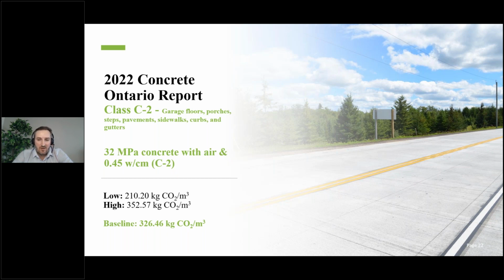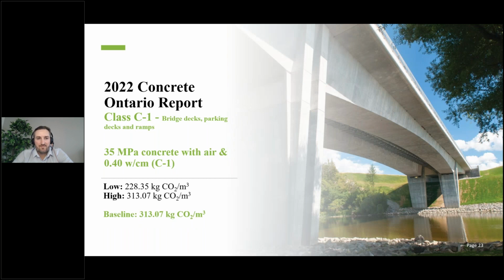And this is again based on industry average information. There are obviously type 3 verified EPDs that are out there where you can get even a much better performance. But overall, this is a great starting point for Ontario to have these values. Another one here, class C1 exposure, so 35 MPa class C1, bridge decks, parking decks, and ramps with a baseline of about 313 kgs of CO2.